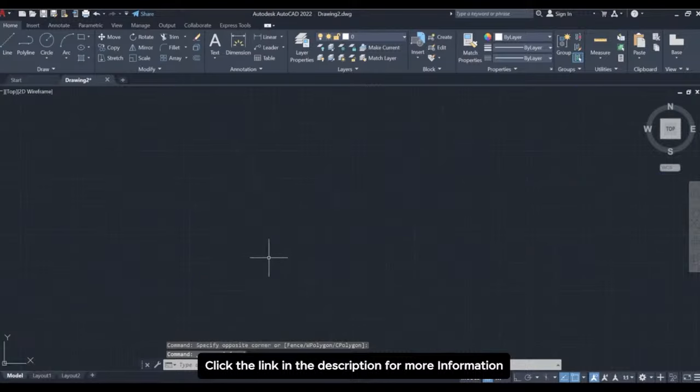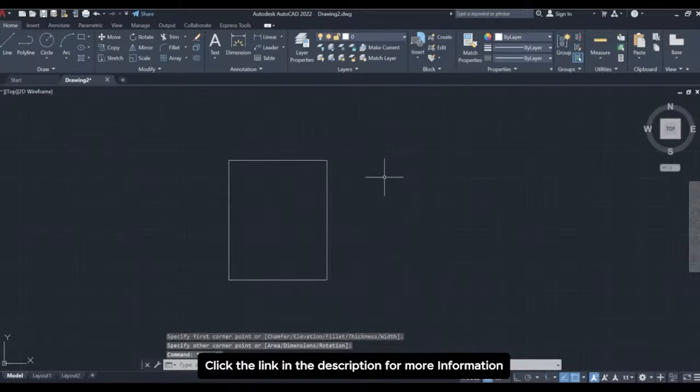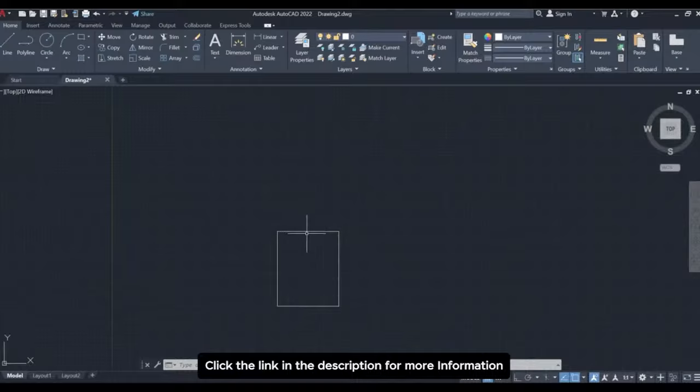And let's talk about center lines. We've discussed center lines in the previous session, but let's talk about them once again. Center lines are used to denote central axes or midpoints of symmetrical objects or features in engineering drawing. For example, if I just draw this rectangle over here, it would look like a normal piece of block. It looks like a square box. But what if I told you that this was not a rectangle, but rather a cylinder viewed from the side, which means that the top view of this object is actually a circle. So how am I supposed to actually denote that there is a center line over here? Without the center line, I'm not able to actually specify what this object really is.